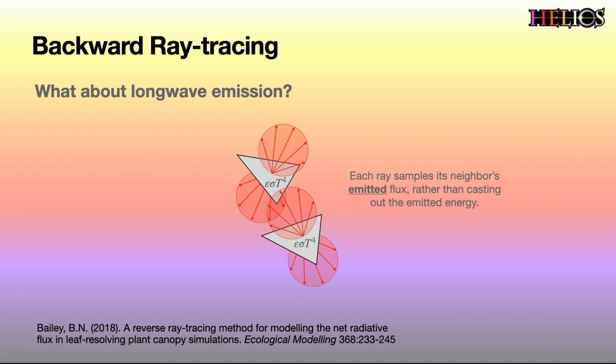What we show in that paper is that especially for emission, using this backward ray tracing approach is really important, particularly when you want to couple it with the energy balance equation, which we'll talk about in future videos. Because even small imbalances in the long wave emitted flux can create large errors in your energy balance equation and give you unrealistic temperatures no matter how many rays that you use. And we kind of illustrate this in the paper using a fairly simple example.